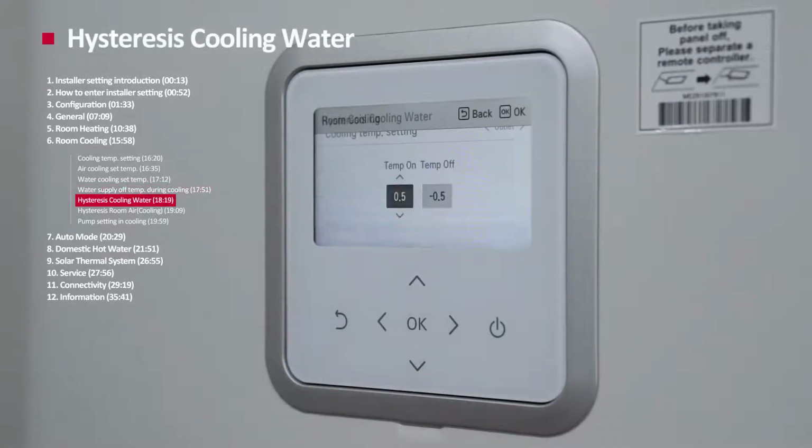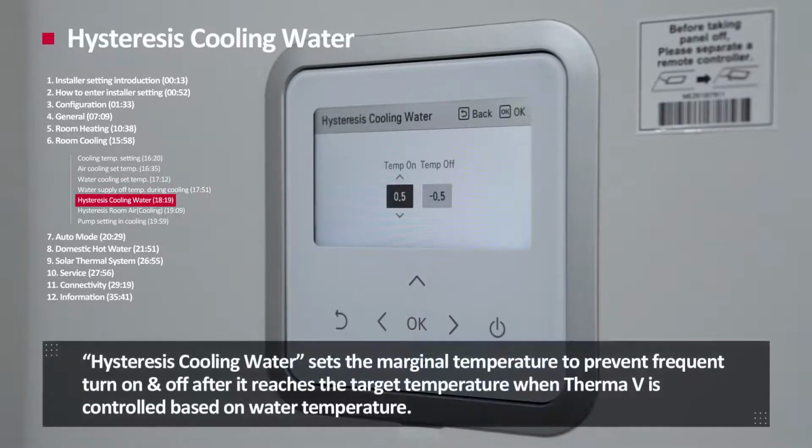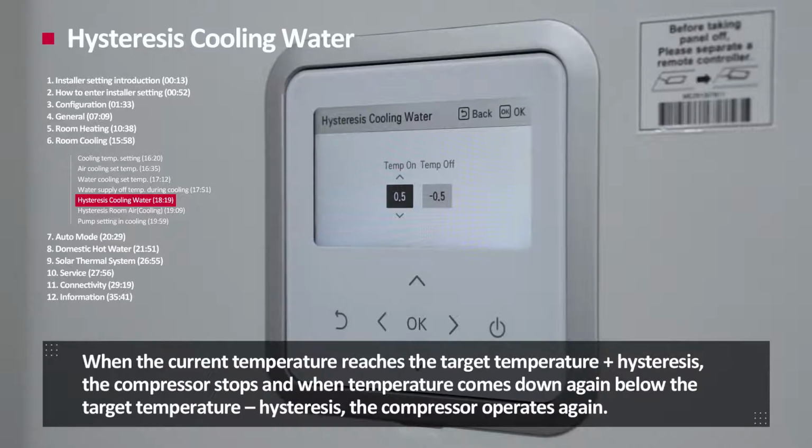Heat hysteresis, cooling water. Heat hysteresis cooling water sets the marginal temperature to prevent frequent turn on and off after it reaches the target temperature when Therma V is controlled based on the water temperature. When the current temperature reaches the target temperature plus hysteresis, the compressor stops. And when temperature comes down again below the target temperature minus hysteresis, the compressor operates again.